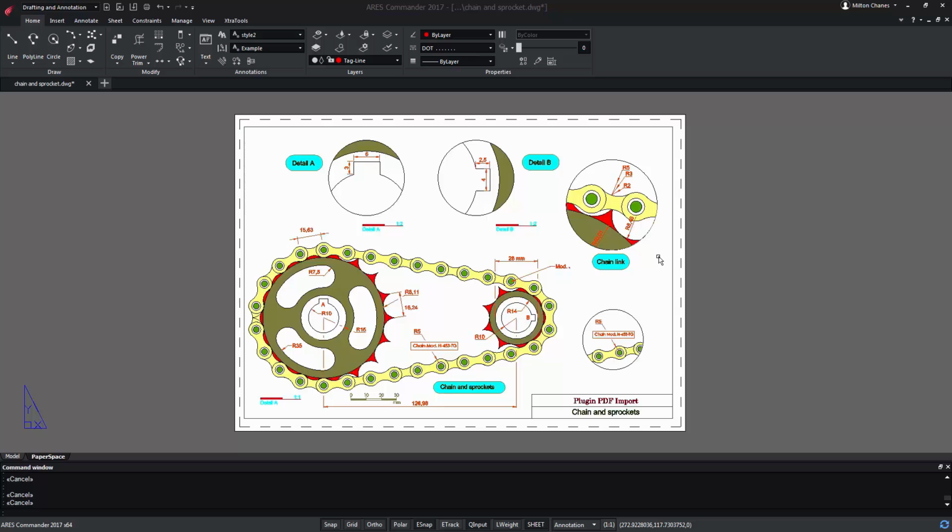When working on a CAD drawing, we will need different line types, also known as line styles in ARES Commander. In this case, for example, the circular viewport contains a line using a continuous line style. We could change this to dots. It is also possible to load other types of lines.